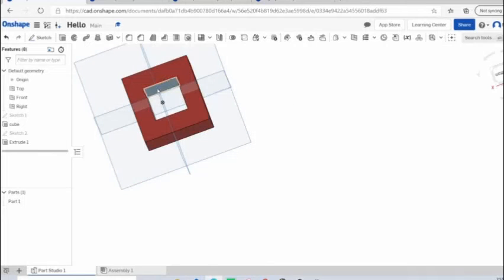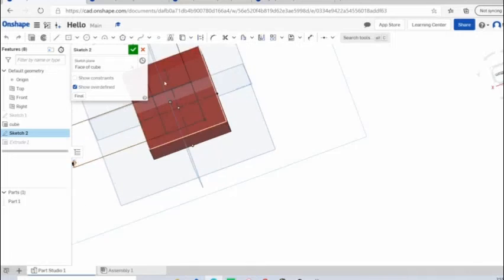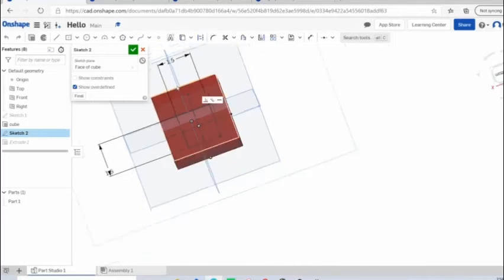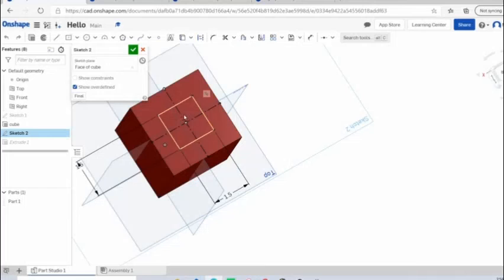And again, that's why we use those midpoints and this coincidence. It allows us to go into our sketch and edit it. Say if we had just defined this as 0.75 inches from this side, we couldn't make our square bigger. But here, since it's already centered, we could actually change these dimensions and it wouldn't wreck our whole assembly.